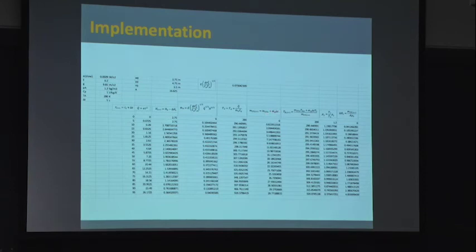So the new mass at the first step is still going to be 0 because there's no heat release rate and there's no mass, okay? And my temperature of the smoke layer is still going to be ambient because I have not put anything into the smoke layer. So then my new density still is the density of air, okay? And my new height, because I added nothing, the change in height is still 0.